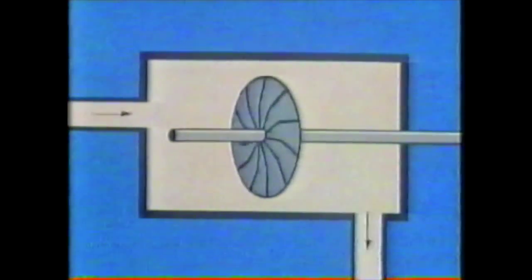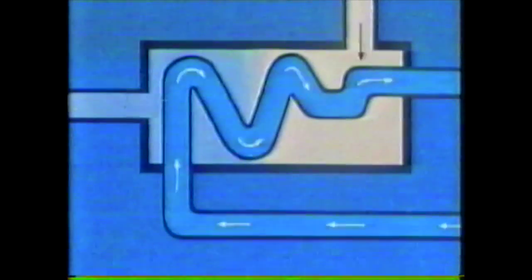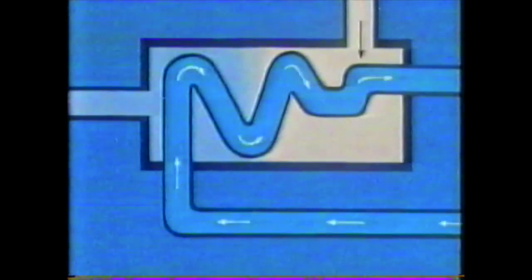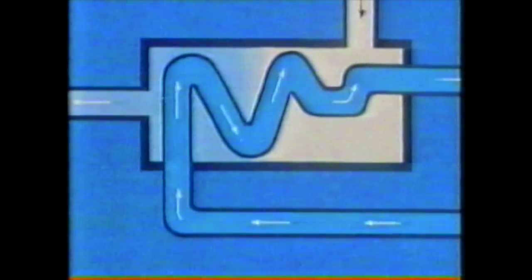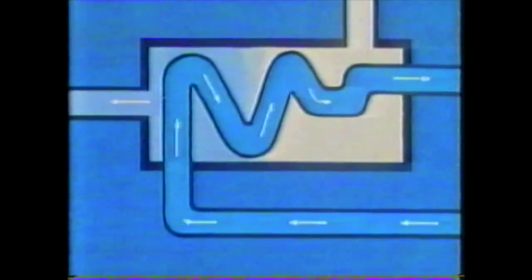The steam which has passed through the turbines is turned back into liquid water in big condensers underneath. The steam is cooled by cold water, passing through pipes. The condensate, the water, passes out at the left there, back to the boilers to be turned into steam again. We don't turn out anything like all the energy as electrical energy. A lot is unavoidably wasted as latent heat in the conversion back to water, but it's made as efficient as possible. Air is needed to burn the coal.